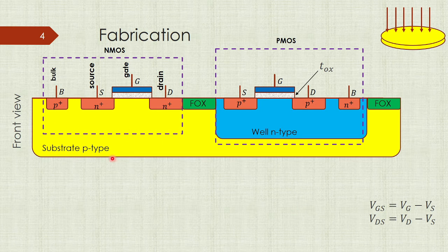After growing this p-type semiconductor, we will grow another type of semiconductor, in this case n-type, for the source and for the drain, and also we will create a connector for the substrate by growing the same type of semiconductor, P, but this will be highly doped. Notice that the substrate is lightly doped, and the source and the drain have high doping concentration.